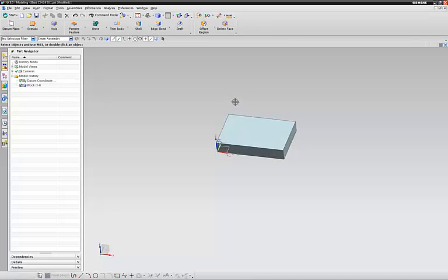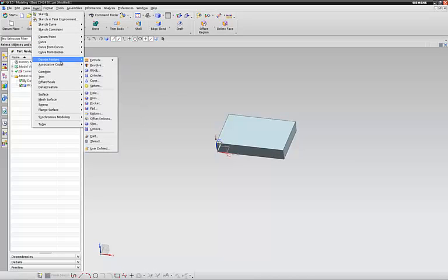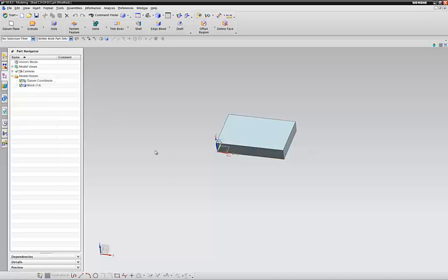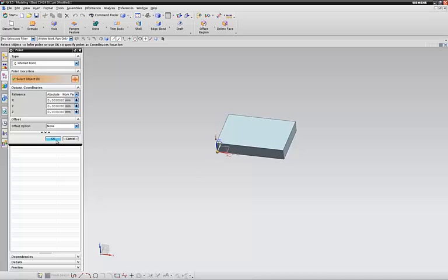Now we want to put the piece over here that we saw, so we're going to insert another block, and its height is the same, and this time its width, the X direction, is not quite so long. That would be only 16. And we're going to do unite, specify a vector, sweet.